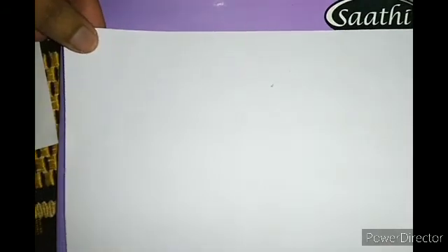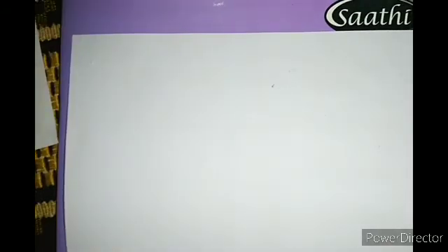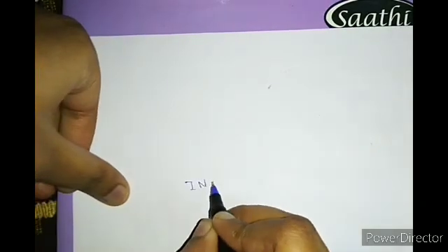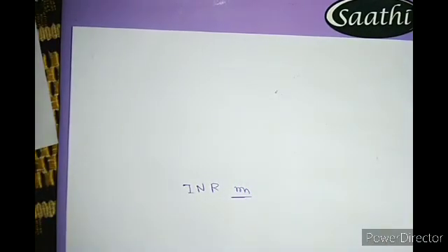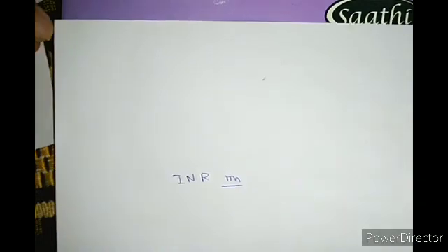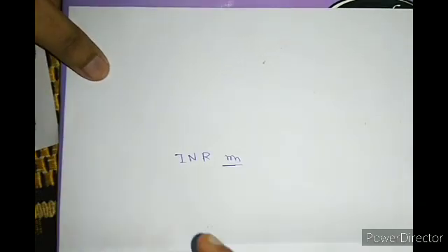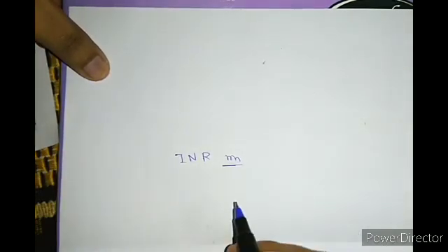The last one for today, and probably the trickiest one. This often comes in exams. In most colleges, the example that comes is MVI register comma data, but INR M. This one is a bit tricky, and I love this instruction. What is M? M holds the data pointed to by the HL pair. How will this instruction get executed?